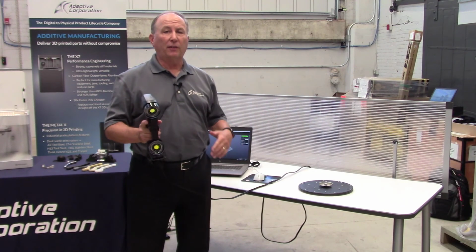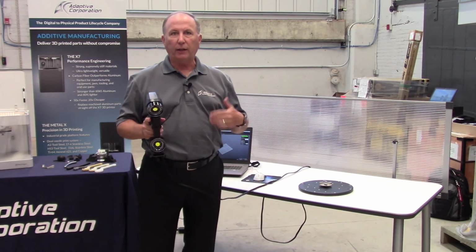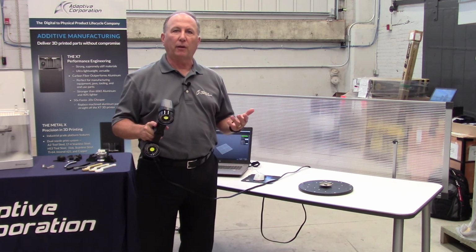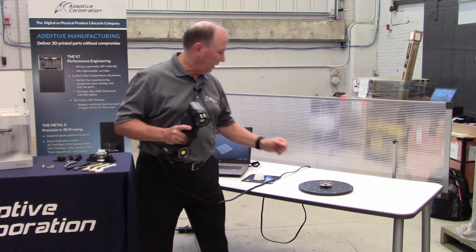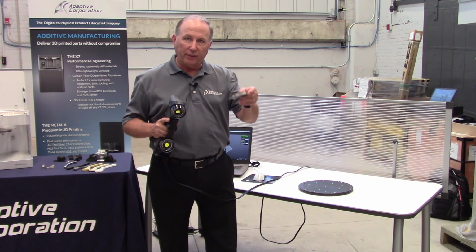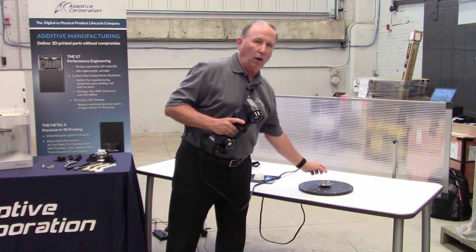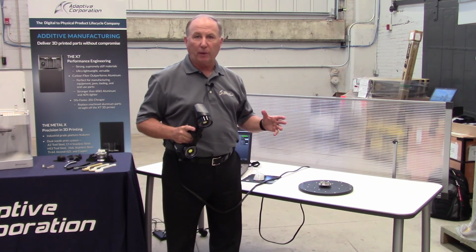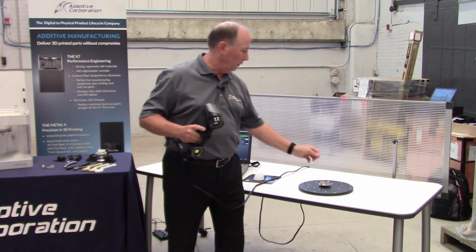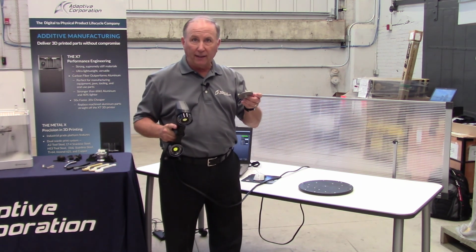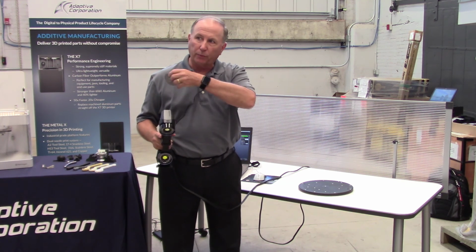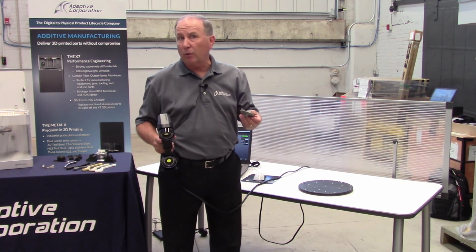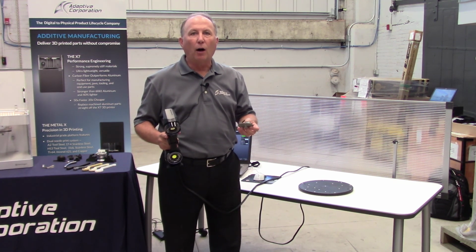The last step in the process is kind of optional. It's a QA/QC process that we employ here in our lab, where we utilize 3D scanning to measure the parts. We can take the physical part and 3D scan it, and then in software we can call up the CAD version of this part. We can overlay the 3D scan of the part, and literally within a minute or two we can tell you if the part physically matches the CAD. So did we get out of the sintering oven, through the entire printing process, exactly what we expected, or if the part is deviating a bit for whatever reason, where is it deviating and how much are we deviating?